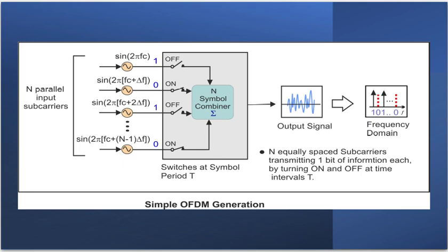Now, what's the advantage of doing this? The main advantage is to battle multipath by having these parallel bit streams transition at a much slower rate. That allows us to have lower symbol speeds and can deal with multipath.